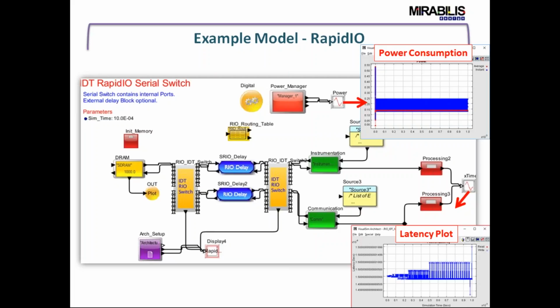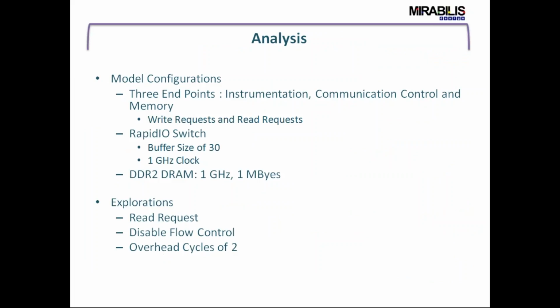So if you have sufficient information about the changes that you could expect in fourth generation or fifth generation, you can enter those details as a set of parameters and try to understand if the system supports the fifth generation of RapidIO technology itself. So that makes it possible to model your custom RapidIO switches as well as the standard RapidIO switches as well.